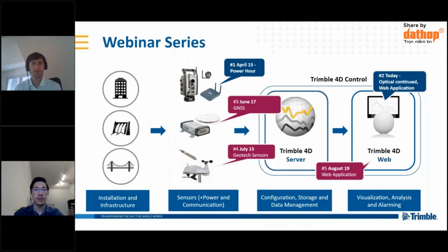Eric was actually chatting me while this is all going on. He moved the target a little bit too far, and so the total station had a little bit of trouble measuring it. Okay, but he's making me the presenter now. We got another round to go through, and we can see it on the web. Yeah, I think the reason was that if you move the target a little bit too far, considering that we have really short distances. In this living room, we have distances of 3 meters. So if you move a target by just 1 or 2 centimeters, it might lead to a situation where the target cannot be found anymore by the total station. But this is a different story. I guess you understand how to create an alarm, and I think that's fine for now.